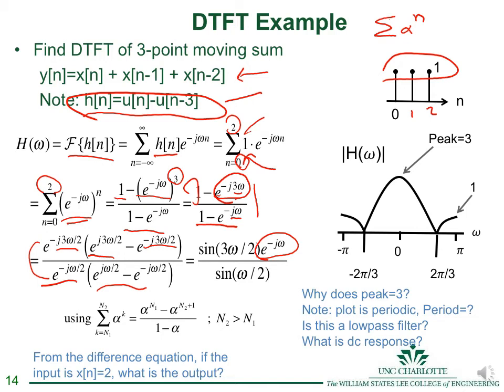There is also a phase contribution I'll mention real briefly. There will be jumps in phase due to the sign. The sine function alternates from positive to negative in the numerator, and so that will introduce jumps of 180 degrees in the phase shift, which we would also see. For now, we're most interested in the magnitude response. We notice that this looks a lot like a sinc function.